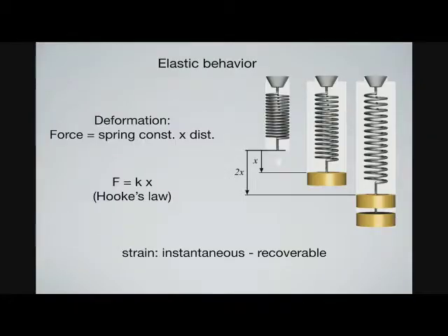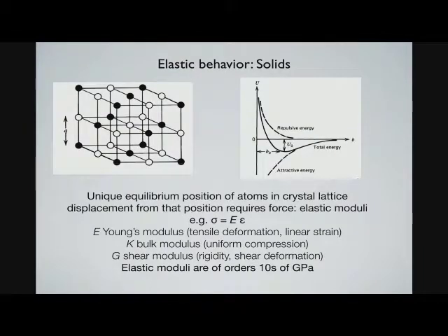So a little bit of overlap, I think, with Phil. He talked about springs and dashpots, I think. So deformation, going back now centuries here, Hooke's law, right? You apply a force, then you have a material property here, the spring constant, and if you apply a force in the form of these weights, then you get an elongation of the spring, right? And essentially what I'll be concentrating on is the spring constant. So there's a linear relationship here between the applied force and the elongation, and the translation here is done by the spring constant.